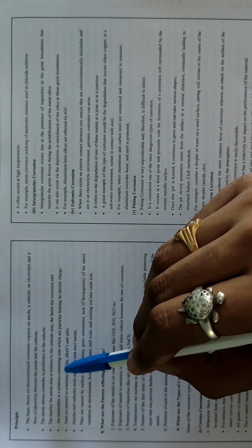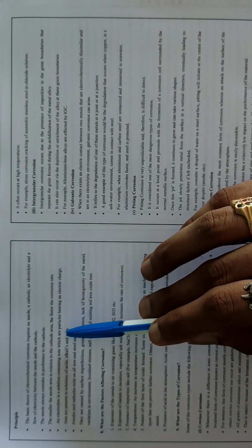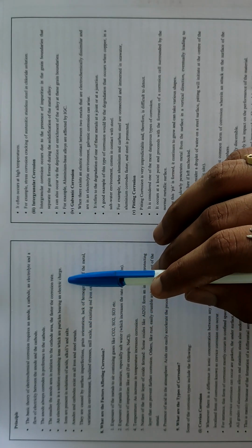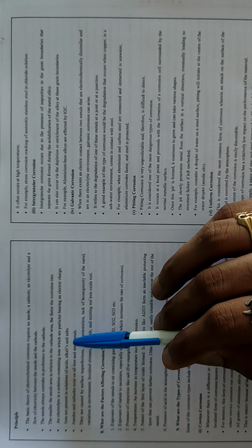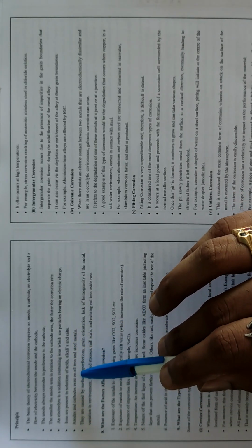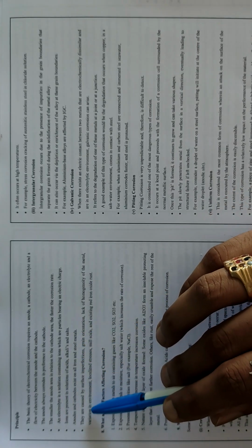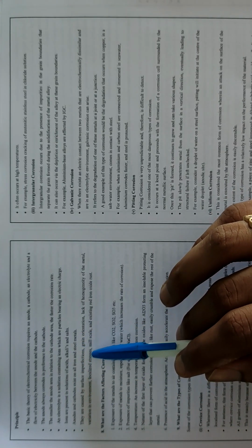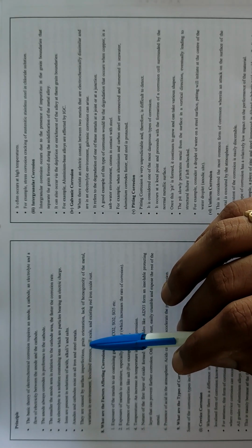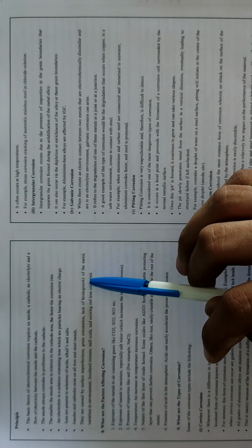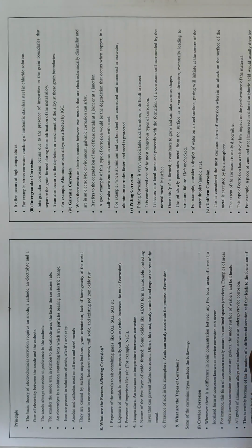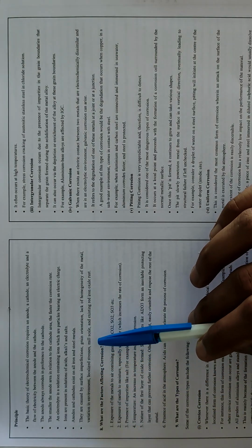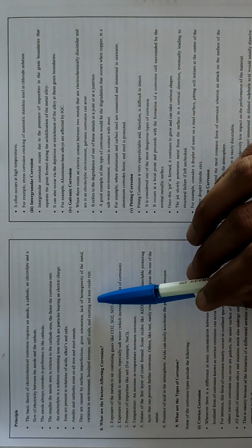An electrolyte is a solution containing ions, which are particles bearing an electric charge. Ions are present in solutions of acid, alkali, and salts. Anodes and cathodes exist in all iron and steel metals. They are caused by surface imperfections, grain orientation, lack of homogeneity of the metal, variation in environment, localized stresses, mill scale, and existing red iron oxide rust.